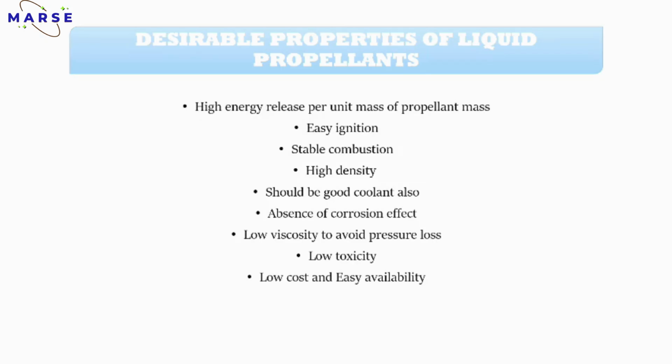If the liquid propellant has high density, it has low volume, so you can store more propellant. Understood? Then next one, it should be a good coolant also.